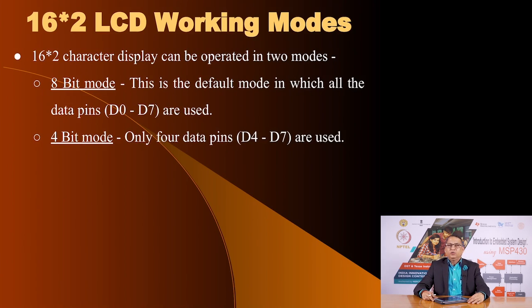Now, because you have 8 pins for interaction, the controller inside the LCD expects you to send commands over these 8 pins, but oftentimes we do not have 8 pins. The Hitachi interface is very benevolent in that sense, in that it will adjust to sending information on 4 bits also. Instead of 8 bits you can communicate with the LCD controller on 4 of the 8 pins, and that is called the 4-bit mode. The default mode is 8-bit mode, but if you do not have pins you can select the 4-bit mode.